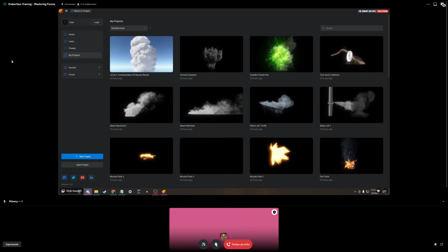So if you didn't know, you can turn any force on or off at any time. So you can go up here to your little on-off icon, and that's one way to turn it off. Or you can animate your activity. So you can click these little circles. That'll add anything you want to the timeline. And you can hold Shift down on the timeline and then click, and that'll add keys. And so if we go here and we say, hey, we want this line force to happen at the beginning, and then we want to turn it off, well, there you go. That's how you would animate a force.